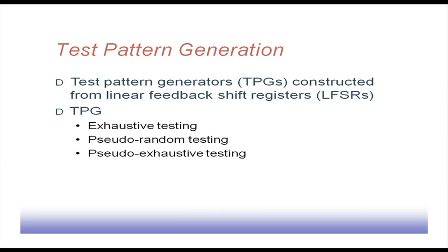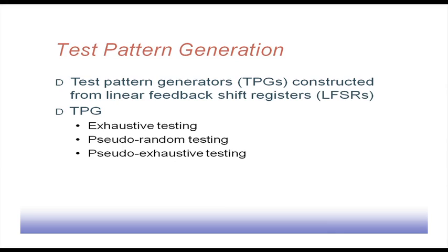Now, how can this test pattern be generated? Typically the deterministic test pattern generator has given us a set of test patterns. As a test pattern generator, we can have a memory where all these test patterns are stored, and a counter that can produce addresses for the memory, and at each count value it outputs one particular pattern that is applied to the circuit. That is the standard ATE type of operation, but when we are talking about BIST operation, we do not have such a sophisticated mechanism.